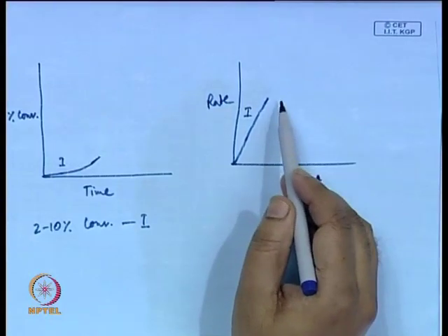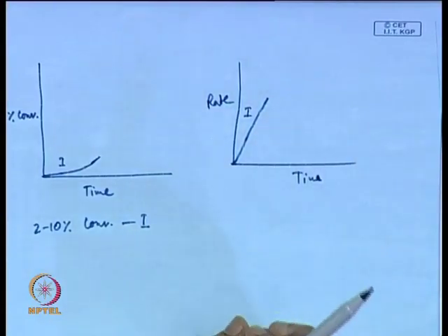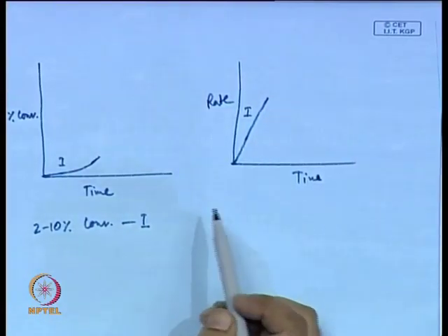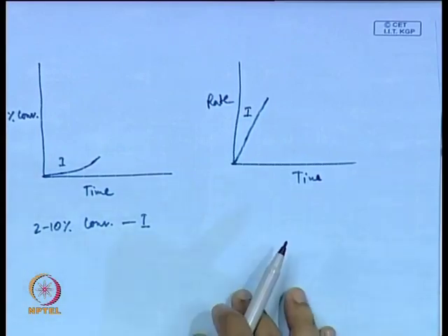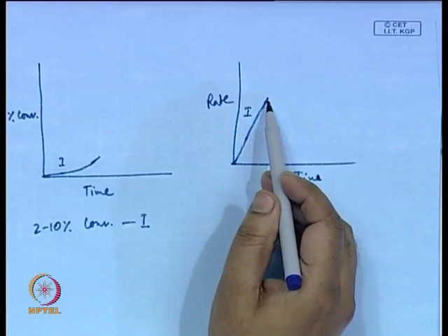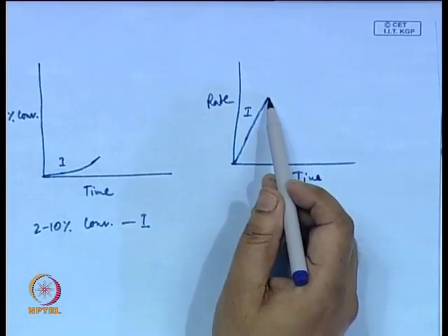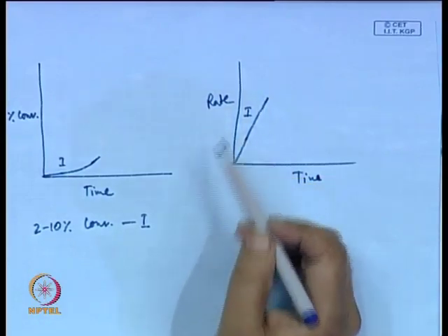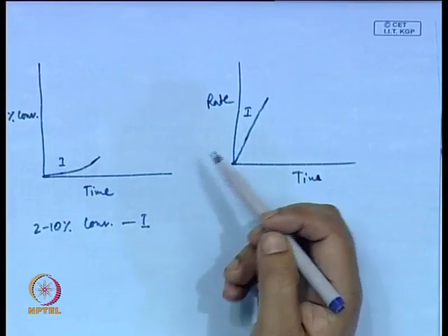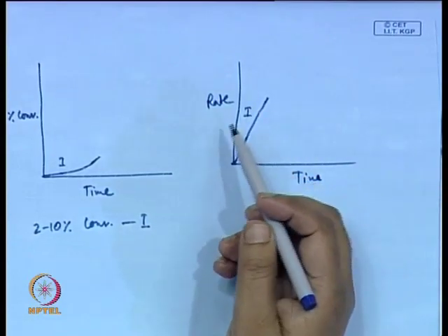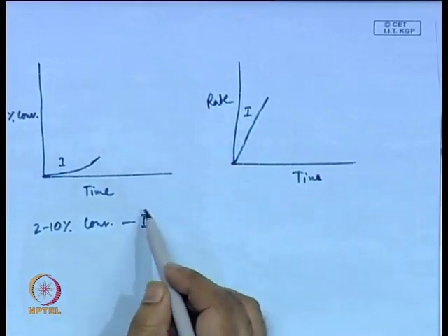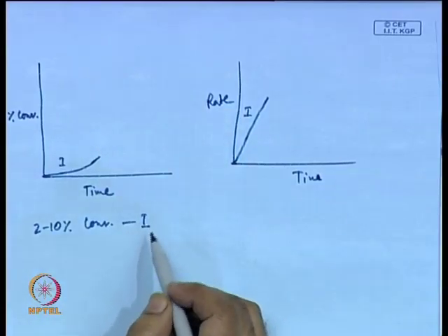So, you have a fixed number of polymer particles plus free monomers surrounded by the surfactant molecules. They are now fixed in number, so no more increase in the number of particles, hence no more increase in the rate of polymerization. That is the end of stage 1.